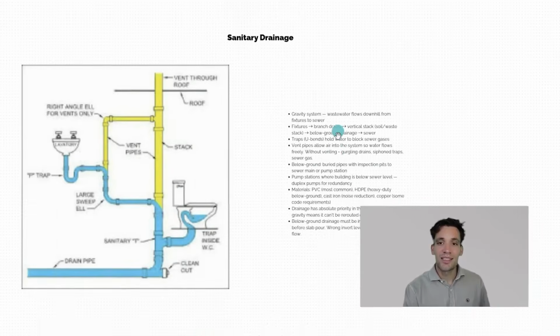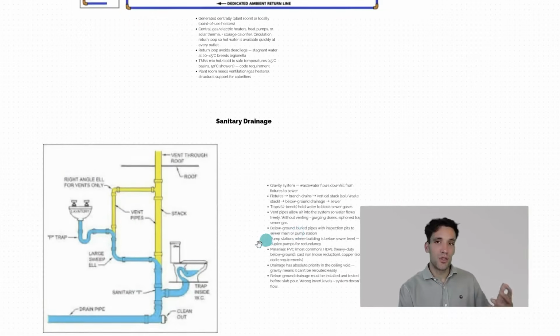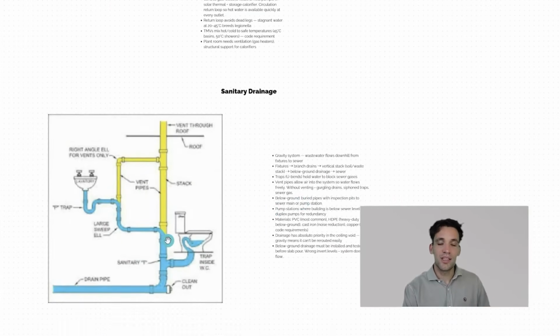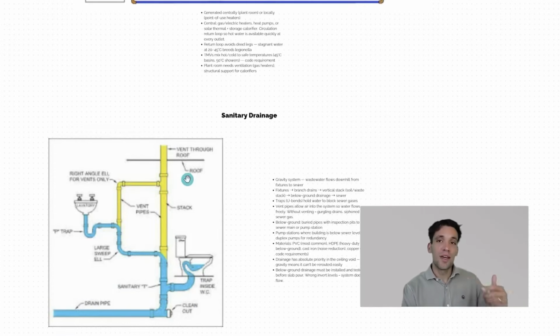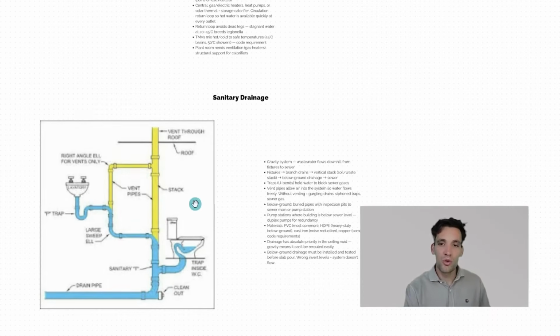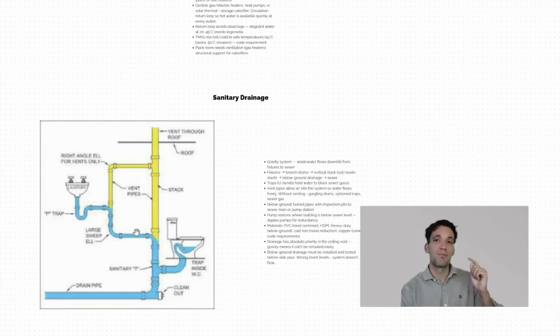Next up, we have sanitary drainage. So this is when you flush your toilet, the water goes down the sink. You have non-pressurized pipework that drains through gravity back into the sewage system in the street. Also, you will have vent pipes that run through to the roof, which prevents the smelly air that sits in these pipes running back up and the smell coming out of the toilet. So that will be sanitary or vent piping that runs to the roof.